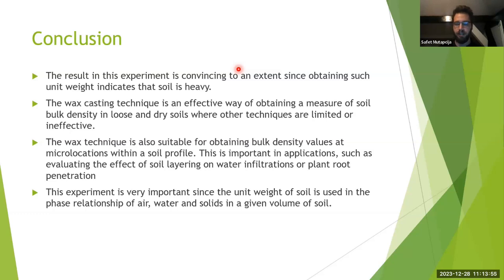For most of the roads it is 30 megapascals, and for some more complex stuff, if you're going to change the soil for your foundation, it is going to be closer to 60. You hire someone who has a device. It's a really simple, cheap one. Basically you have a plate weight, and you have your soil there. Just put it there. The plate weight is going to fall in free fall from 1 meter.